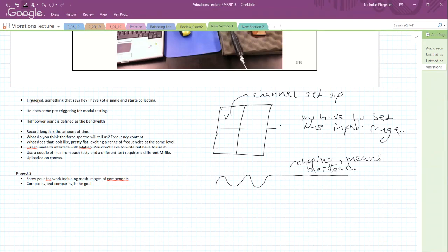Normally, when you run that test, you actually start taking data. When it's going through the range of speeds, it doesn't matter. Once you start taking data, you want the 3 green lights on each channel. What that indicates is you're using whatever range you set. You can tolerate a little bit of yellow, but you don't want any red. In the audio world, with mixers or any sort of preamp, you usually have some sort of indicator light that's overloading. You tolerate a little bit. Same thing.